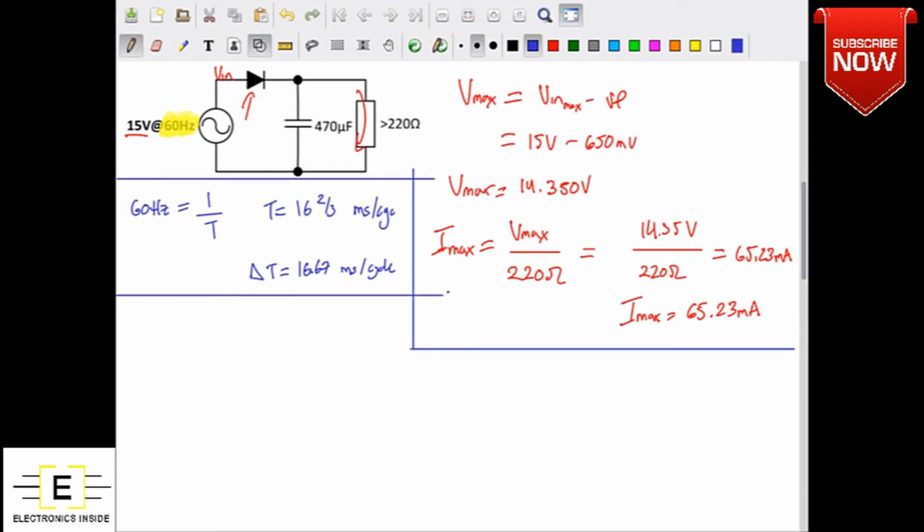Okay, so let's take these two trains of thought and see if we can use them to figure out what the maximum supply ripple is going to be. If we remember our very basic description of the capacitor, we said that capacitor current occurs when we have a change in voltage. The amount of current that occurs for a given change in voltage depended on the physical ability of the capacitor to store charge, or its capacitance. So our fundamental capacitor relationship was that I, or current, was equal to the capacitance of that capacitor times the change in voltage with respect to time.